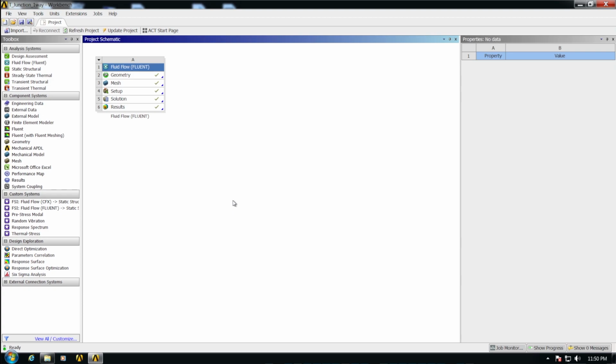It's extremely important at this step that when you restore the archive and save the project directory, that you do this to a local hard disk. Do not save to the network drive. Do not save to a USB memory stick. Do this to the local hard disk on the machine that you're working on. If you do it any other way, you will encounter an error later in the lab.